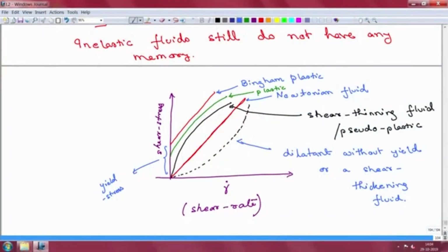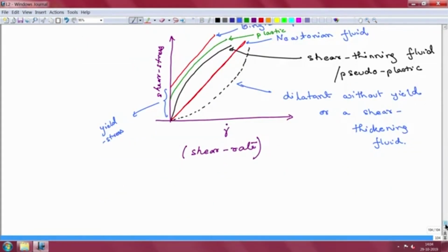Of these models, one of the most important ones is this pseudoplastic category, and I will just make some space for me to write here. So, pseudoplastic, as we said, or shear thinning: polymer melts. So, we had seen earlier that one of the largest classes of soft materials or viscoelastic fluids that we have encountered, maybe the term soft material is more appropriate here, are the polymers.